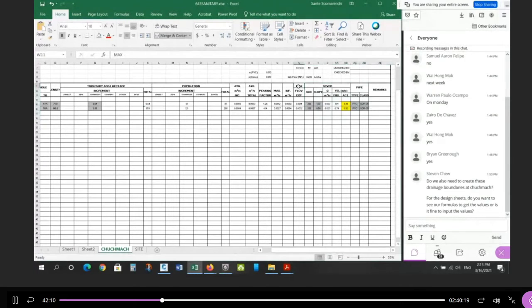So this is your flow determination. What's the expected flow based on people and peaking factor and so on. And then on this side, we now look at the capacity and velocity of a pipe and make sure that the capacity of the pipe is greater than the expected flow. Okay, so that's the second part of this. Any questions so far before I get into the pipe calculations?